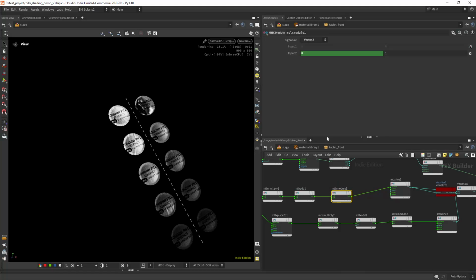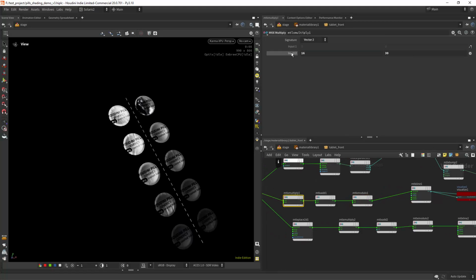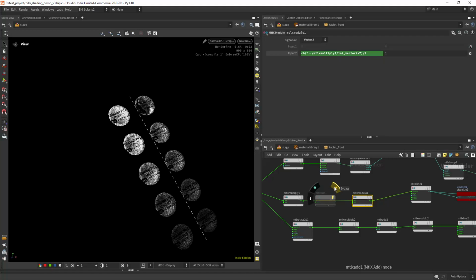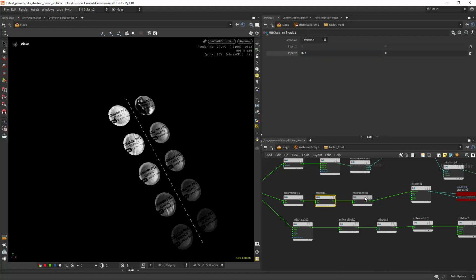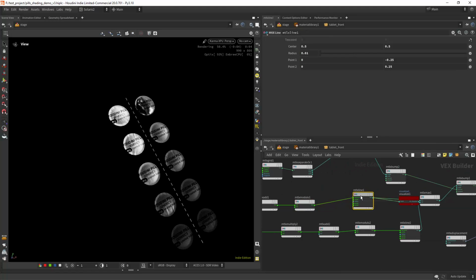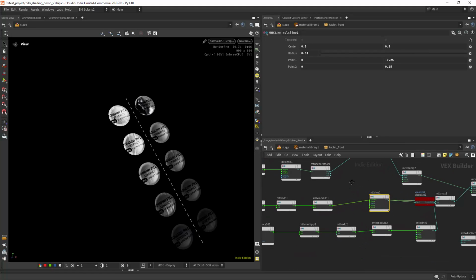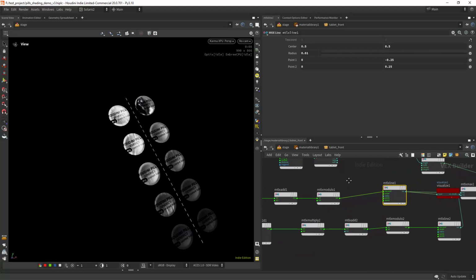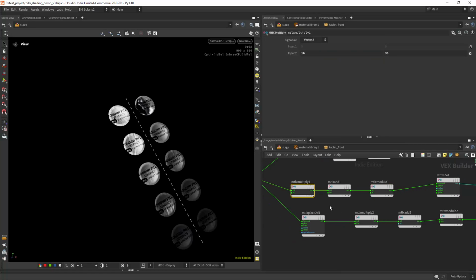What I need to do actually is use a modulo to repeat the texture, to repeat the pattern. And I'm using the scale X divided by 2 in here, since I want it in the center. And as you can see, these add nodes just make everything work from the center instead of that random position. So yeah, that's how you can repeat MaterialX line and other patterns that are non-tileable by default, using the modulo along with the multiply.